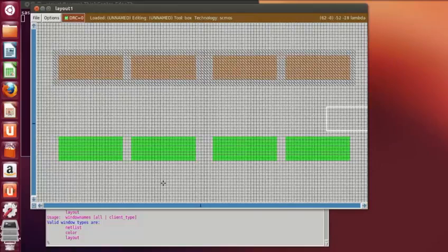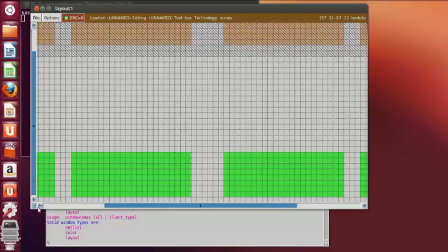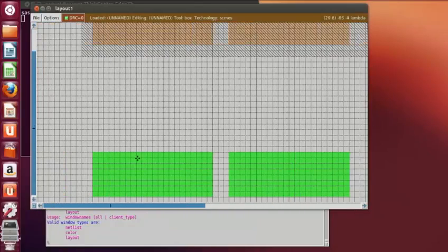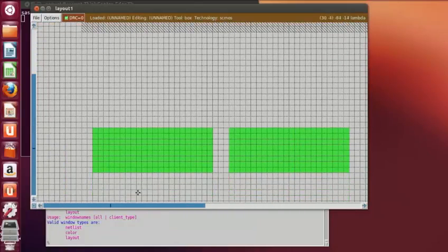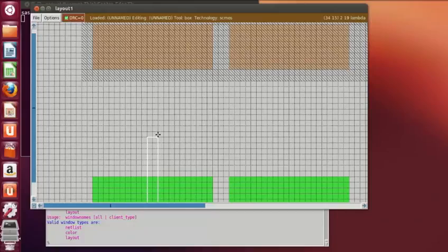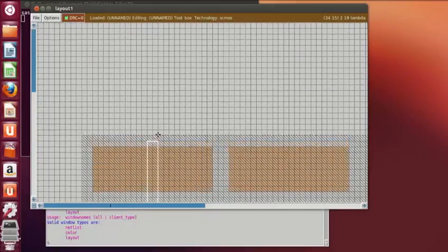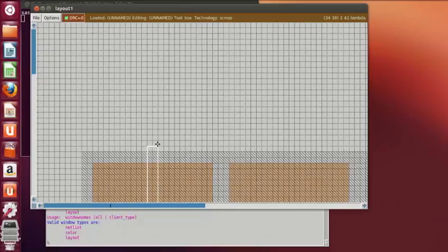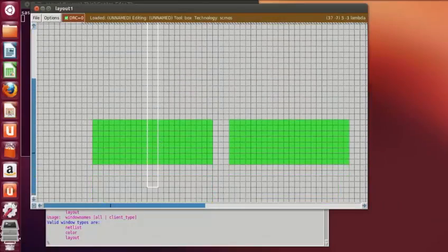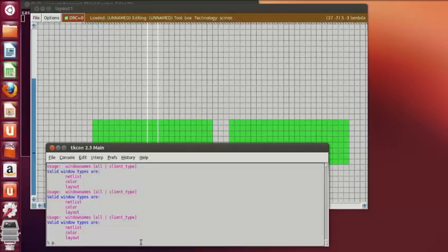for transmission gates. So in order to draw the inverters, first you have to draw the gate, that is the input. Zooming in helps us to find the width or draw according to the width. So this we have taken as 2 lambda. Okay, we can place over here. Now paint poly.